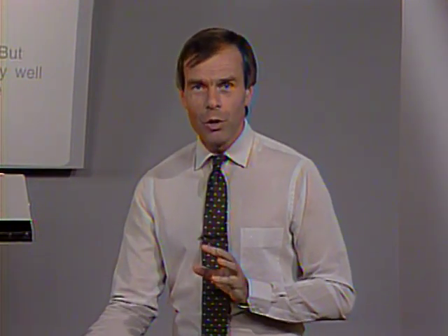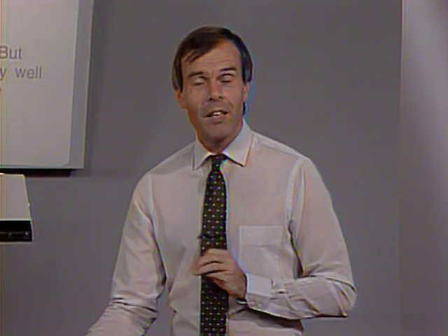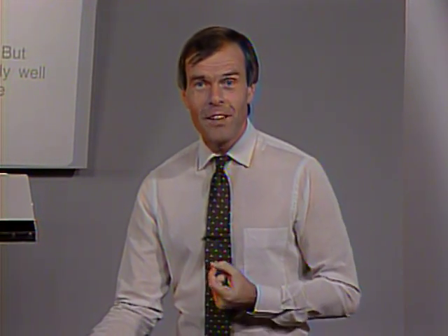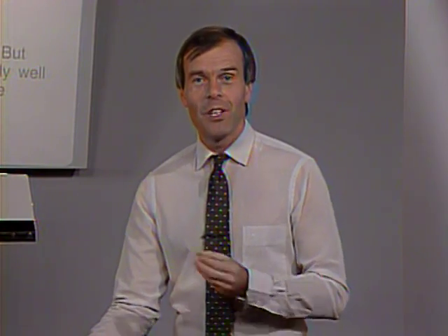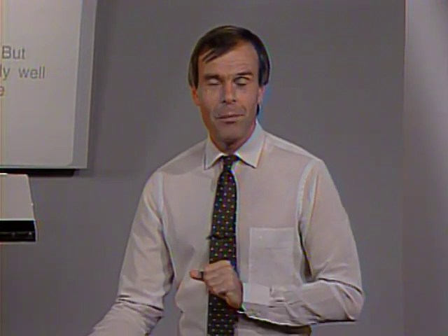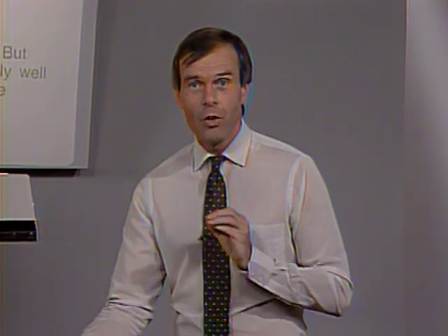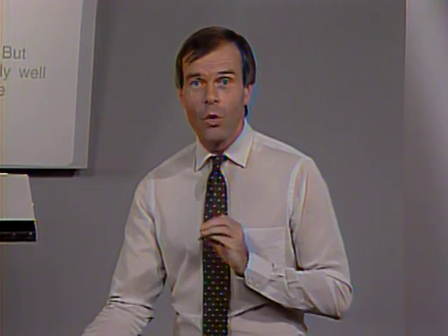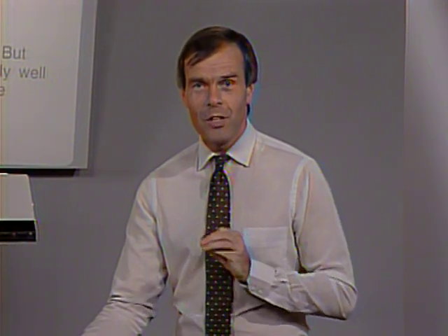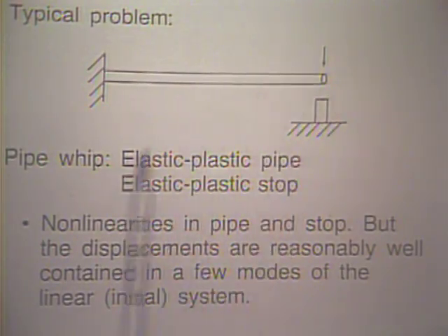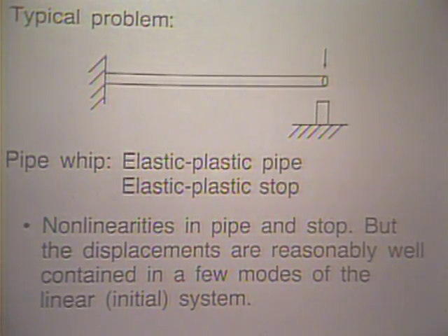If you only include a few mode shapes, the solution is quite inexpensive, but the accuracy is not very high. If you include as many mode shapes as there are finite element degrees of freedom, then of course you get the exact response. All you have done is transformed from one basis, the finite element degrees of freedom basis, to the mode shape basis. But then the solution is very expensive and you don't want to ever do that. The point is that you want to perform such analysis if you only need to include a few modes in the response solution. We will actually look at this problem, or such a problem, a little later when we discuss example analyses.